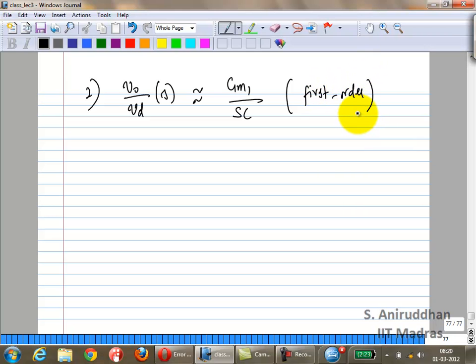Okay. Remember, from when we went through the control systems model of this, we always wanted to realize an integrator. We came up with this two-stage topology because we had certain constraints, and we added the capacitor across as a transimpedance. But at the end of the day, you want to generate some GM over C, GM over SC kind of function. So this is what we are shooting for, first of all.